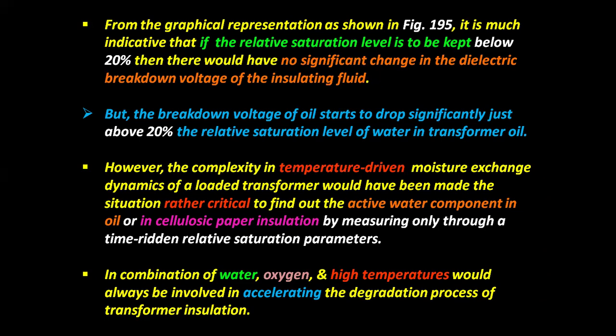However, the complexity in temperature-driven moisture exchange dynamics of a loaded transformer makes the situation rather critical for finding the active water component in oil or in cellulosic paper insulation by measuring only through time-dependent relative saturation parameters. The combination of water, oxygen, and high temperature would always be involved in accelerating the degradation process of transformer insulation.